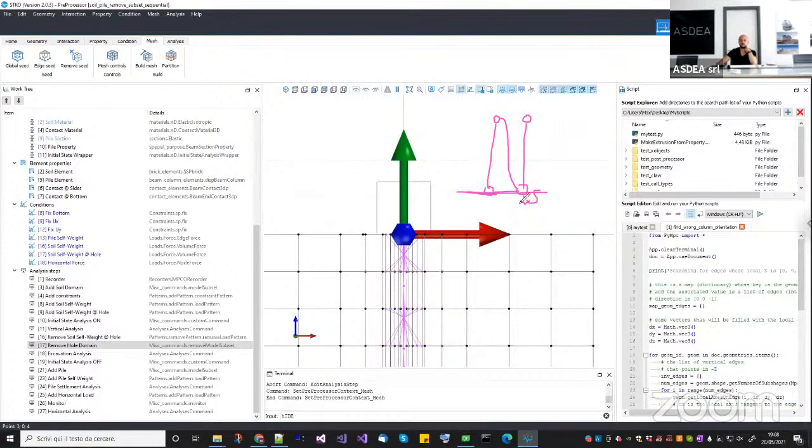I am enlarging this tolerance a little bit here, but imagine this is a very small number, like this is 5 and this is 5.00001, or actually 4.999, so a little bit down. This one will not be in contact because it will not find the other beam element, because this one is connected to this beam element. But down here, it will not find any beam, and so it will not find contact, while actually there is another beam element down here.